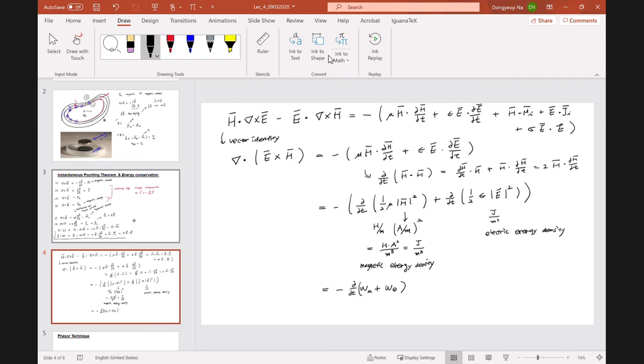And what would be the left-hand side term? The units are volt per meter and amperes per meter, so the unit of the resulting field is volt times ampere per meter squared. What is volt times ampere? That would be watt, which is the unit of power. So it's going to be power density.